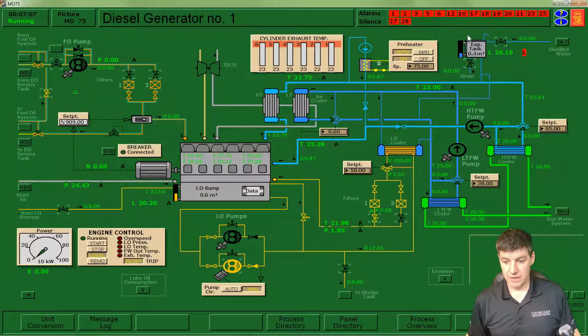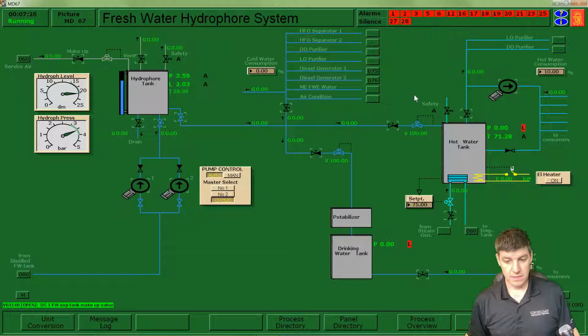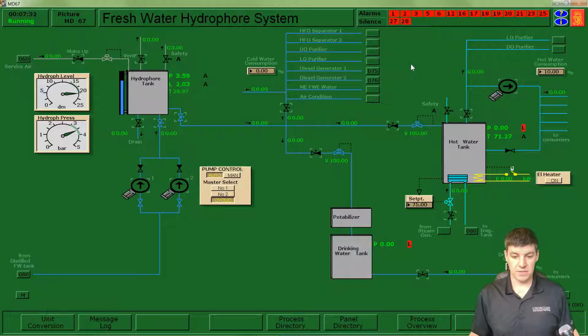I also noticed that my expansion tank is low. So I'm going to try opening up this valve. However, I see that it's not providing me with any water. So I'm going to backtrack. So I'm going to keep going back to 6.7 and remembering that I just came from 7.5 again, and I'm going to look for where that connection is to the system. And I can see it in this bank, number 7.5.